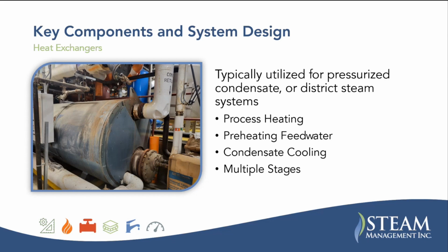Condensate cooling is sometimes necessary if the condensate is very high pressure and the feed water system is very low pressure. It's just beneficial to use some of that heat before you send it back to the deaerator. And then sometimes there's multiple stages where you're dropping down pressures and flashing off at different pressures for different system pressures that the facility may have.